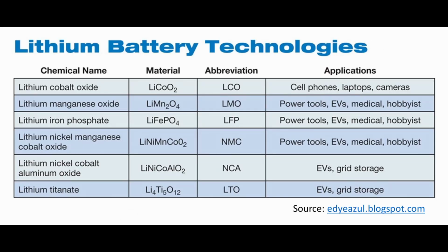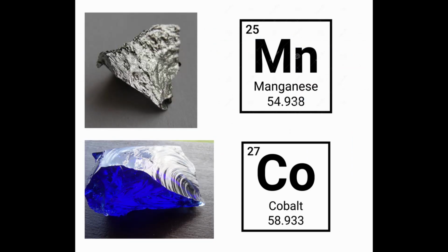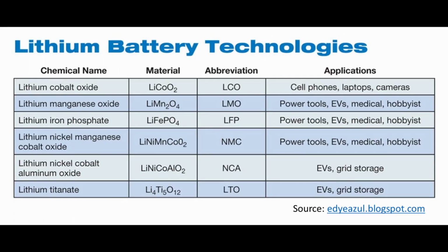There are many other forms of LCO degradation that reduce the LCO battery lifespan. Similar problems reduce the lifespan of other batteries in the lithium-ion battery family to a greater or lesser degree depending on the battery component materials. Although cobalt is the favored cathode material for lithium-ion batteries, manganese-based cathodes are more desirable because manganese is more plentiful and less expensive than cobalt. Manganese-based batteries have less energy density than cobalt-based batteries. Often, the less expensive manganese-based cathodes are doped with cobalt to improve energy density while keeping material costs down.